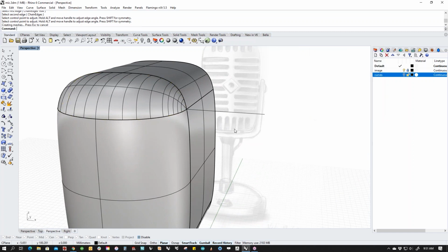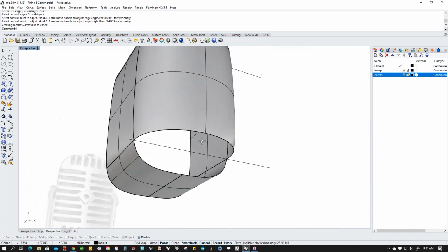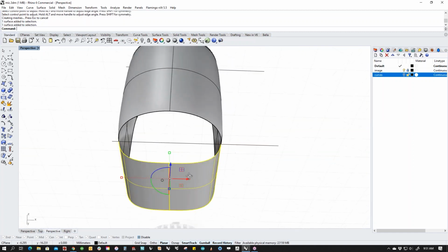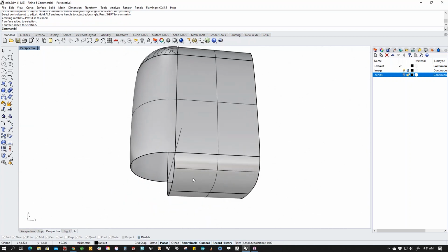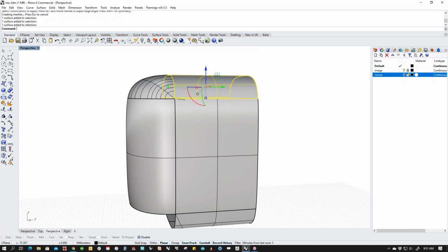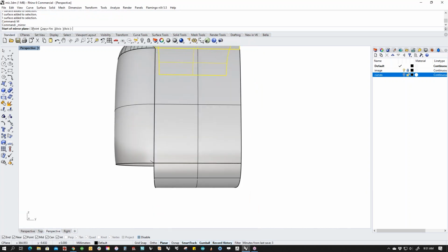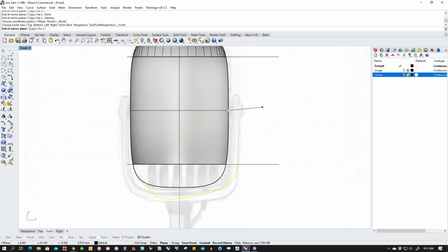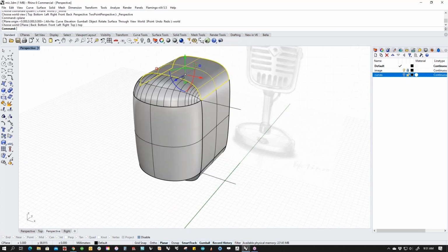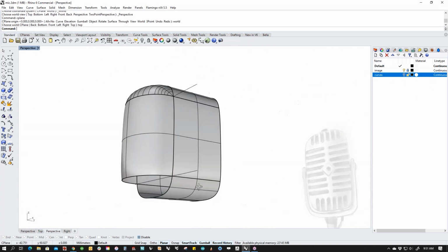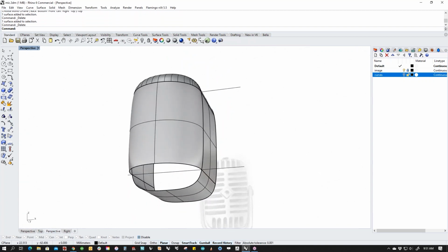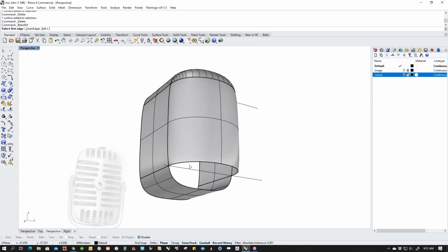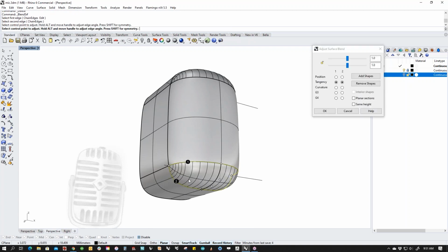And that looks pretty good. And then, see how that's broken into two pieces? I don't like that. There had to be a seam somewhere. So I'm actually going to mirror this piece at the center line and use it down here instead, because I want that cleaner version. I don't want to have a seam in it. So then let's blend this again from here to there.